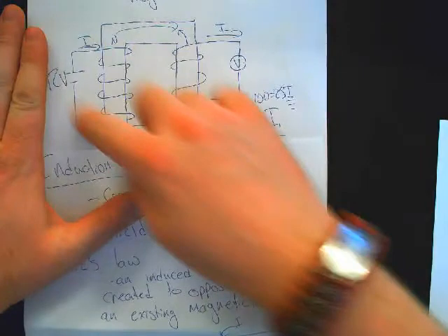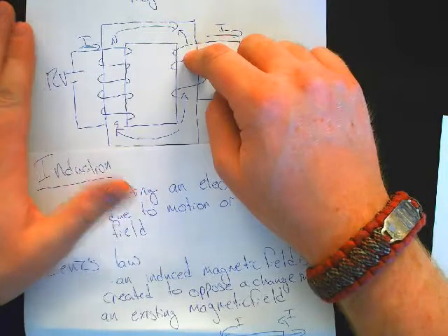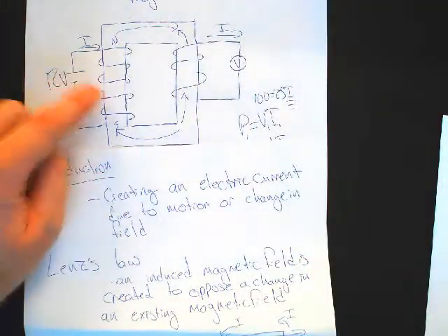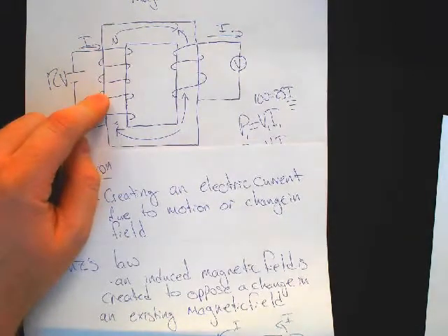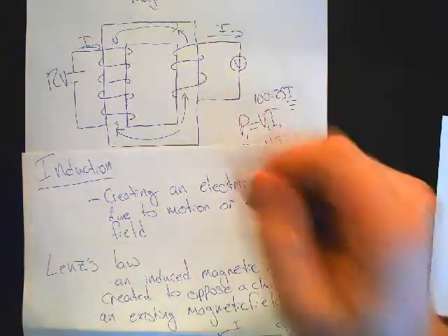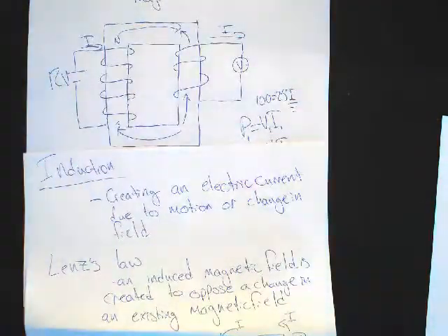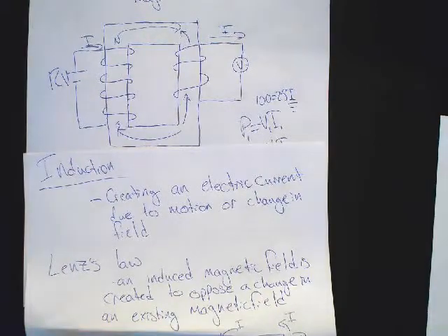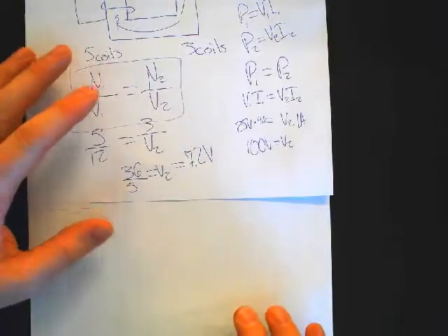If we're using direct current, nothing changes, then this only turns on the counter field that instant that this thing was turned on. That means there are two ways that I can get this transformer to actually work. What's one of those ways? Constantly flipping it on and off and on and off. So I've got continuous change. Every time I turn it on and off, this creates a magnetic field in opposition. I get current here. Good. There's the first answer. What's the better answer? Anybody know? Using alternating current. Okay. So rather than using direct current, transformers only work on alternating current.